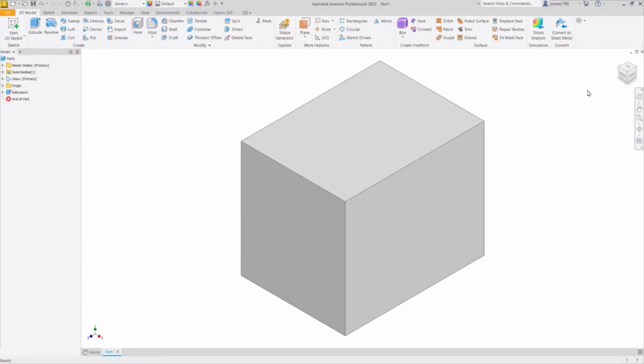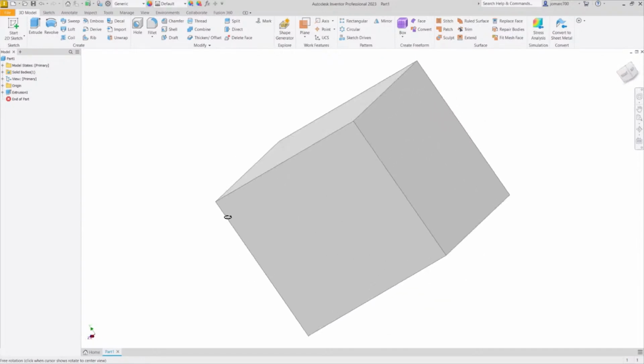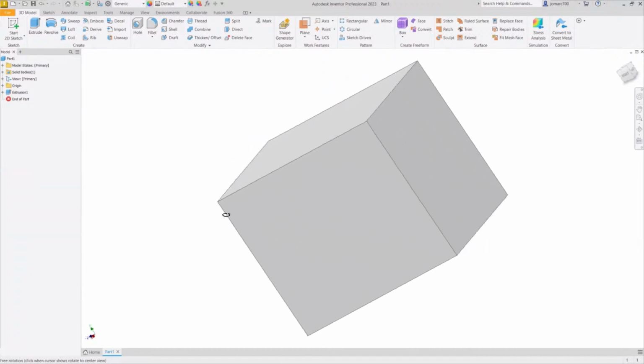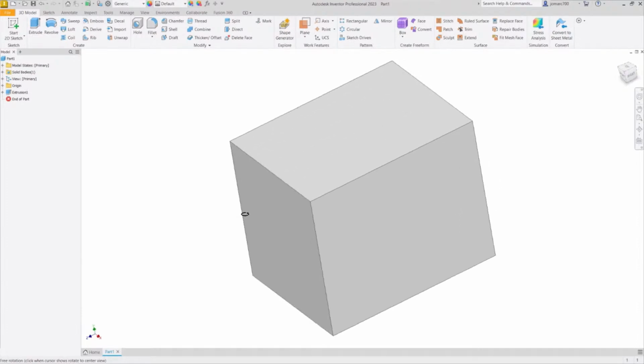And lastly, sharing with you the last option to rotate our 3D model is simply hitting F4. Notice as I hit F4, we have this circle and these lines. So notice as I hover over this line, notice the change of my cursor, and as I left click and move my mouse, okay, I am rotating this object with respect to a vertical axis.